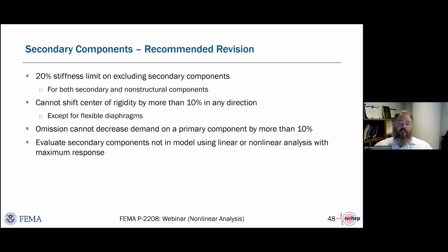And in a case like that, especially for older buildings that did not require design for amplified shear forces like we do now in concrete structural walls, this can be an issue, and this outrigger effect can be significant and can change the behavior of the wall from force controlled to shear controlled. So this is another caveat that has to be checked.